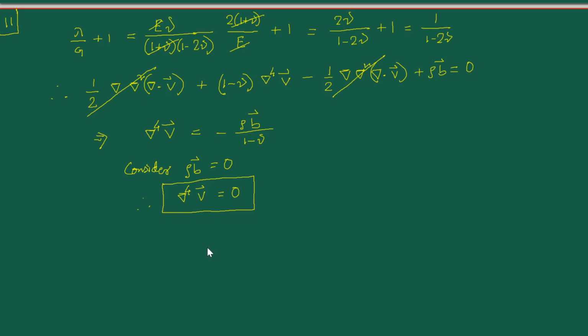And if you refer to our textbook by Martin Sadd, you will see that the solution to the Kelvin's problem has been given stemming from this Galerkin potential, and the way it has been given is that you have been supplied with a particular form for this V vector, and you have been asked to basically check that it satisfies the conditions for the Kelvin's problem. We will be taking a slightly different route, and for that we'll discuss another kind of displacement potential called the Papkovich-Neuber representation in the next lecture.